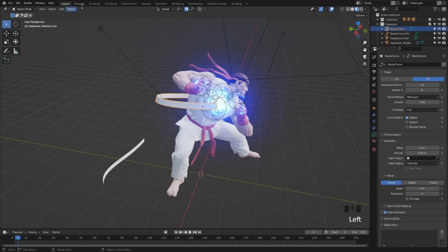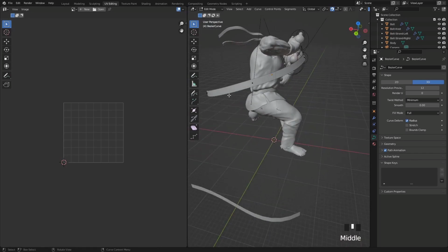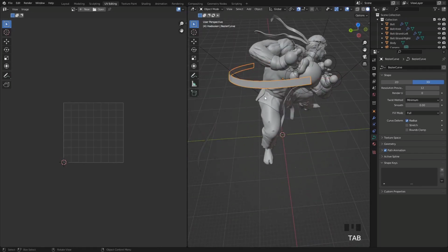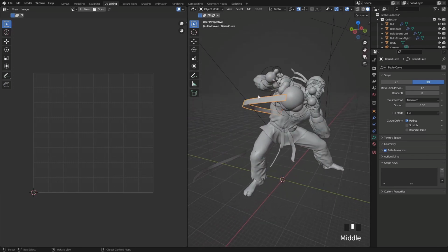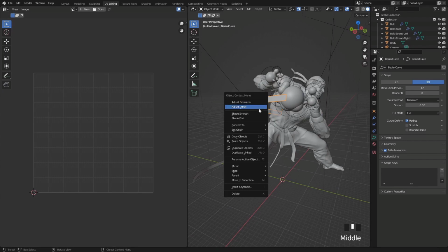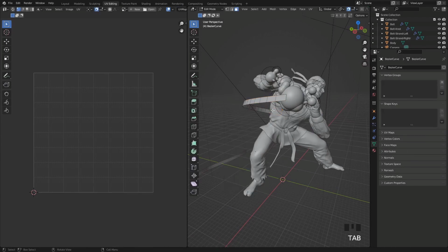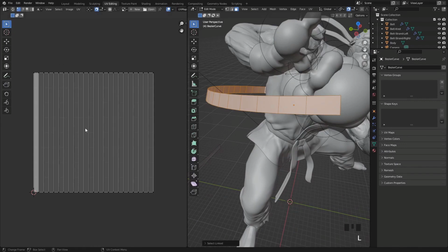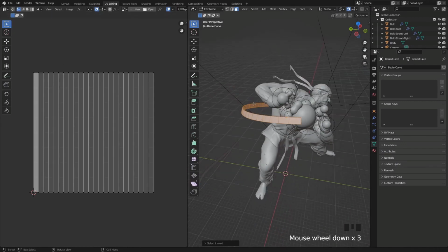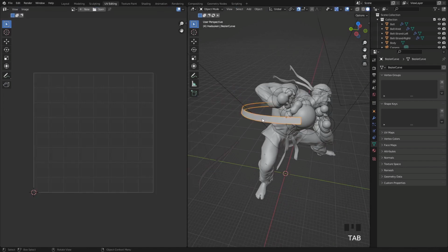So, to get started, if we take a look at the UVs of this spline, there's not really any, because it doesn't really exist. And that's going to be kind of important for the texture we're going to make, because we're going to use the UVs of this ribbon to make a shader based off of its UVs, which is going to be the square. So a way I can show you how to do that is by selecting this, right-clicking, and convert to mesh. Now, if we go into edit mode, you can see that there is UVs, and if we select all of them, there they are, showing up in basically the UV space. So this is what we need, because we're going to go ahead and make a texture or a shader based off of this UV map that you see right here.